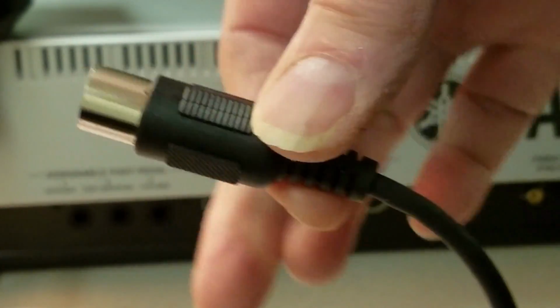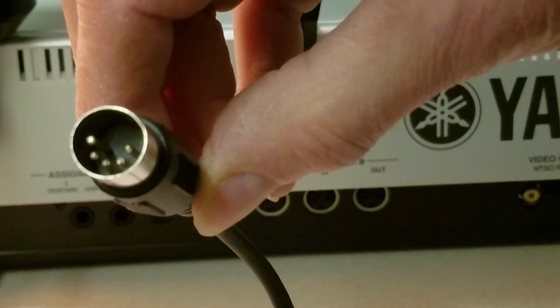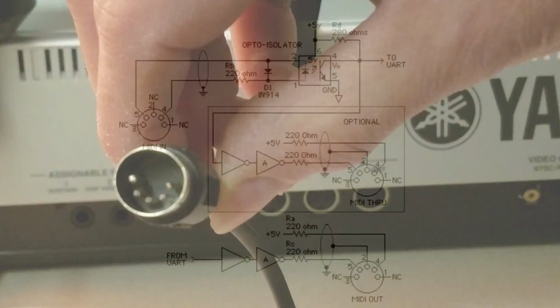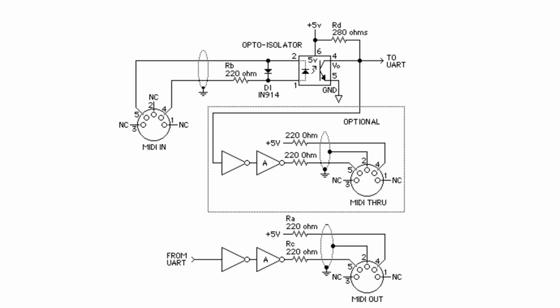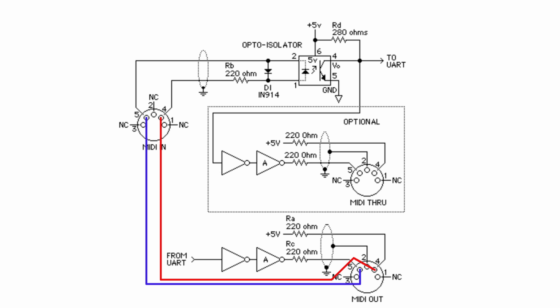Standard MIDI cables consist of shielded 2-conductor cable terminated by 5-pin male DIN connectors on each end. Information only travels in one direction from the MIDI out connector on one device to the MIDI in connector on the other. The cable completes a current loop where plus 5 volts on the transmitter produces no current and represents a mark. Ground creates a current in the loop and represents a space. The signal is in a marked state when it's idling. To eliminate the interference that ground loops could cause, there's an optical isolator in the receiver, and the shield is only attached to the MIDI out instrument.